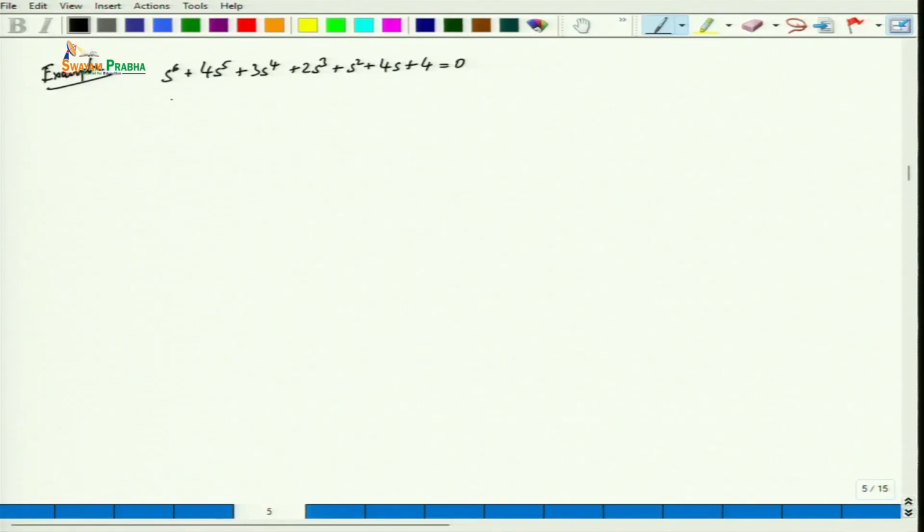So first thing we will check is the necessary condition. If we check this polynomial, we will see that all coefficients are positive. So our necessary condition is satisfied. So we will now check for the sufficiency condition by formulating the Routh array. So let us start with s to the power 6. We will arrange the coefficients, and if you do not have any corresponding value, you set it to 0.